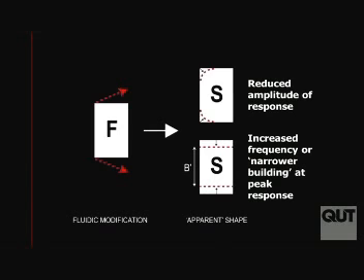This is really just an exploratory study that we undertook, and the way we're interpreting this is that the fluid is doing two things. It's reducing the overall amplitude of the response. By injecting fluid, we're making it easier for the wind to go around the structure, and that allows the wind to see effectively a more aerodynamic profile. And the frequency is changing, and that's really saying that the wind is now seeing effectively a narrower building. So we're reducing the load.